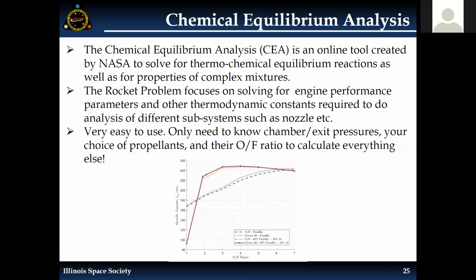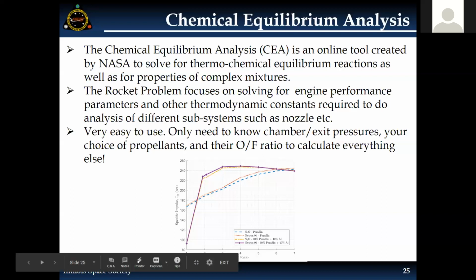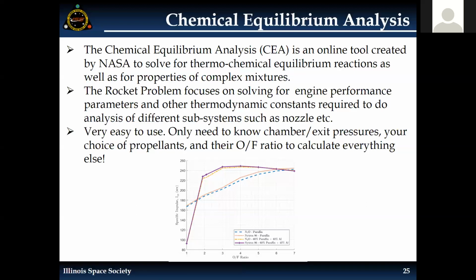I had a quick question. Correct me if I'm wrong, but isn't oxygen the best oxidizer? Are we not using LOX because it's hard to keep as a liquid, since you have to keep it really cold? Right. Yeah, LOX is the best oxidizer. That's why most liquid propellant rockets, like the really big ones, use LOX and liquid hydrogen as propellant choices. But it's definitely way more difficult to work with, and it's also very difficult to store. Those are the challenges it has.